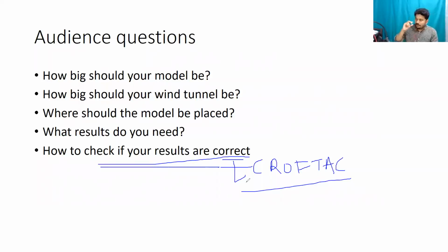Now, obviously, you are not going to get the results in one attempt. You will get the results only after 15 or 30 or 20 attempts. Especially when you're a beginner, you need more attempts. But finally, you will get the right answer. Take the settings that you used, like the mesh settings, the turbulence model settings that you used, apply it to your F1 car model, your FSAE or Baja models, and then use it. Only then you can be sure that your CFD simulation is the right simulation, or else you're just performing CFD simulations for the sake of it.